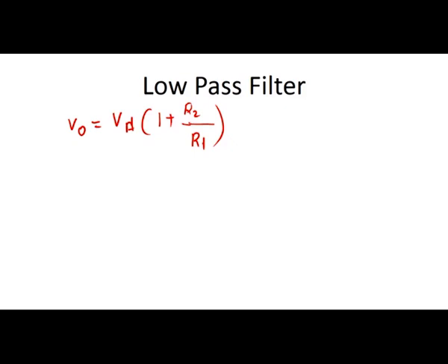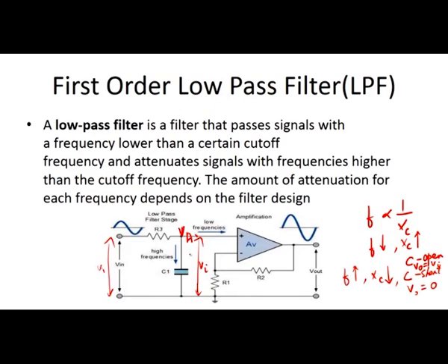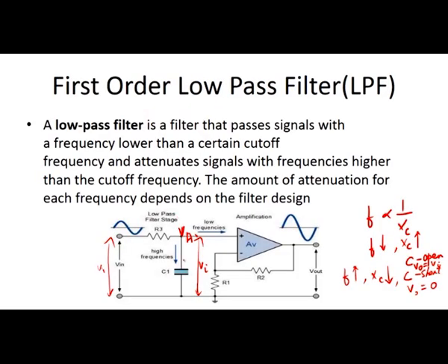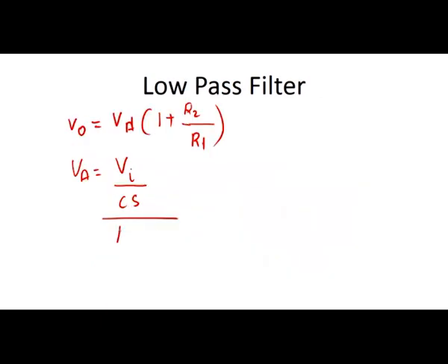So, now what is VA? VA is the voltage across the capacitor. For this, with the input signal given, we use the potential divider rule to calculate the voltage across the capacitor. So, Vi times 1 by Cs divided by the total passive components R plus 1 by Cs. I am taking it as R and Cs instead of R3 and C1.